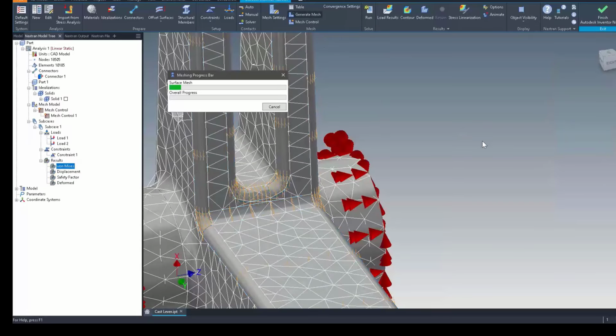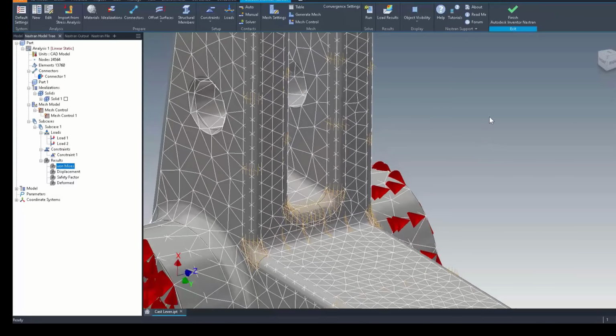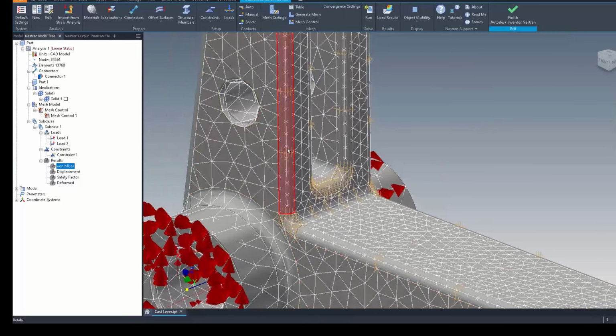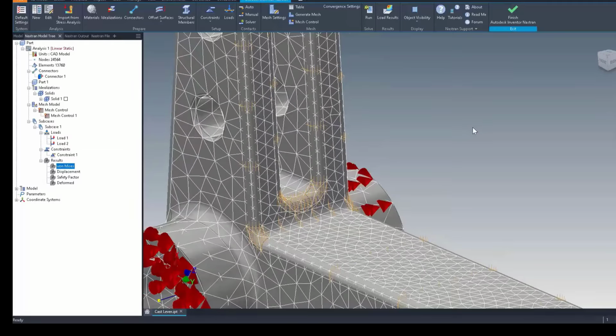So go ahead and generate the mesh, and you'll notice the mesh in and around and connecting to those areas will get smaller and adjust to fit it. So any surfaces that contact the surfaces being refined, that surface will have mesh adjustment along that contacting vector or along that contacting edge. So the global mesh automatically adjusts to incorporate that local control.